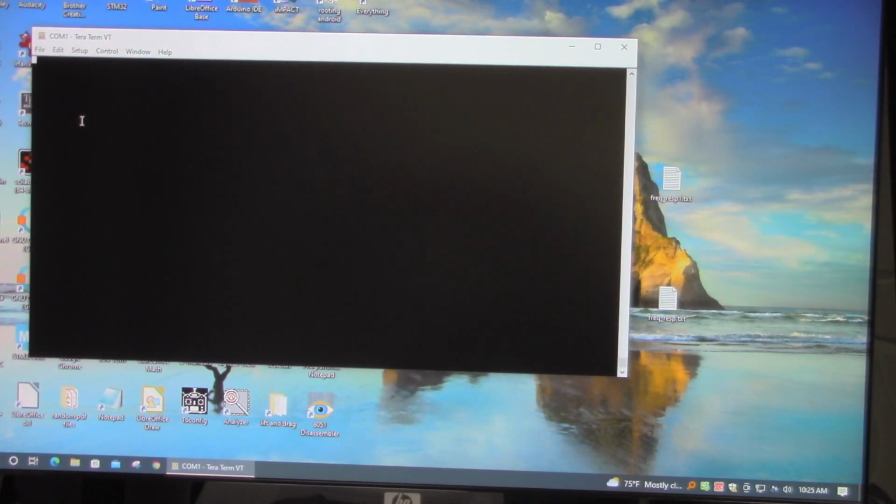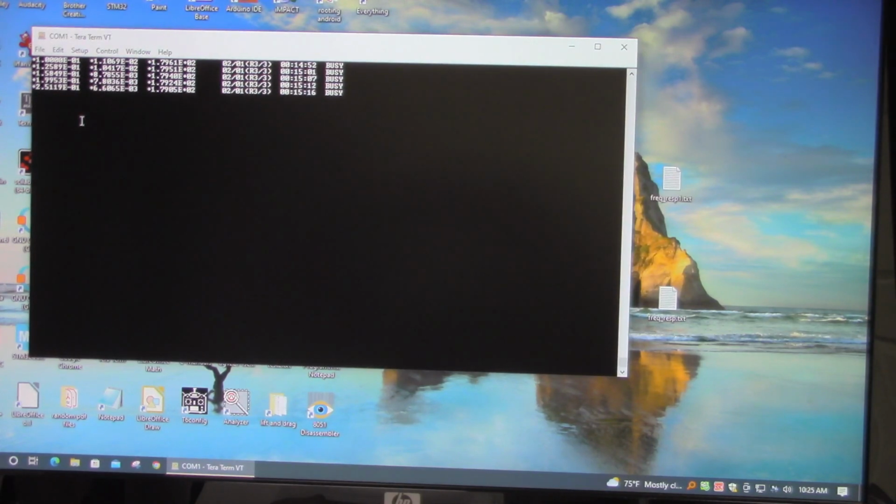And the way it works, we set that integration time to 2 seconds. So it's either going to take 2 seconds or 1 cycle, whichever is the longest. So there you go. There's our 0.1 hertz sample. And with a low pass filter, the dB is close to 0, and it's about 180 degrees because of the inversion. If it was a non-inverting op amp, it would be around 0 degrees. So there it goes. You could see it collecting the data there. It's up to 0.251 hertz, and it's going to sweep up and do 10.